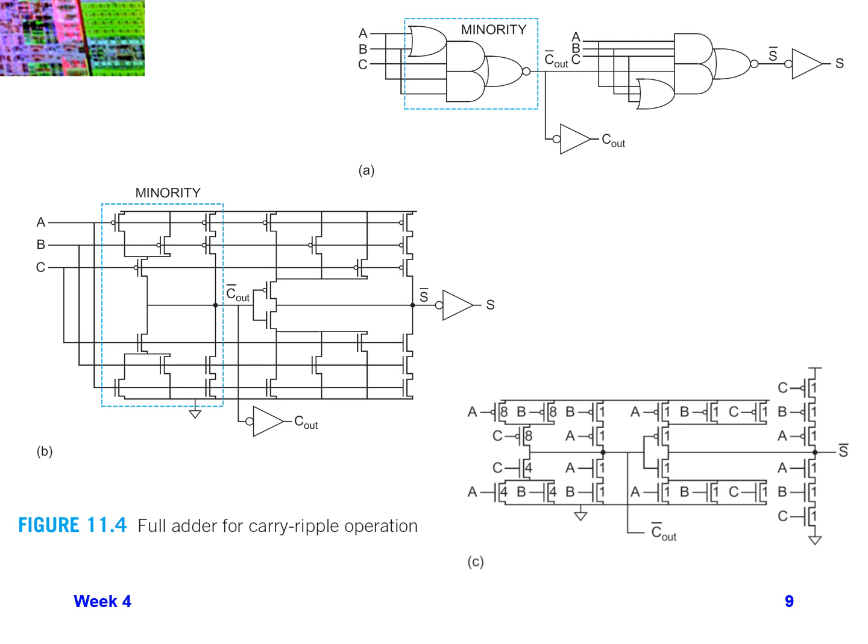The reason why we're using minimum size gates for the rest of it is because it's not in the critical path, and if we make it smaller, it will actually allow the C out to go out faster because there's less parasitic capacitive load on the C in to C out path, and we can make the overall layout size smaller for this gate by making the rest of it small.